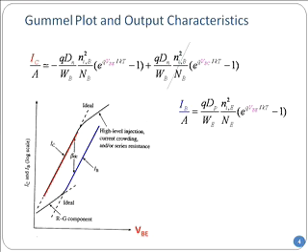But you realize one thing, that if it is a good bipolar transistor and you are taking a signal from the air, from the antenna, which is the base current, let's say, and pumping it into your loudspeaker or whatever speaker, in that case, if I_C is not bigger than I_B, then you are not going to listen to any music.